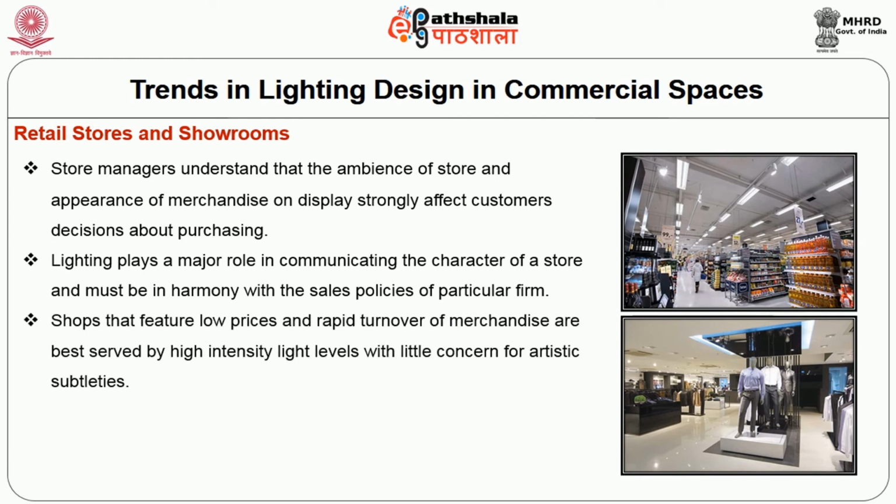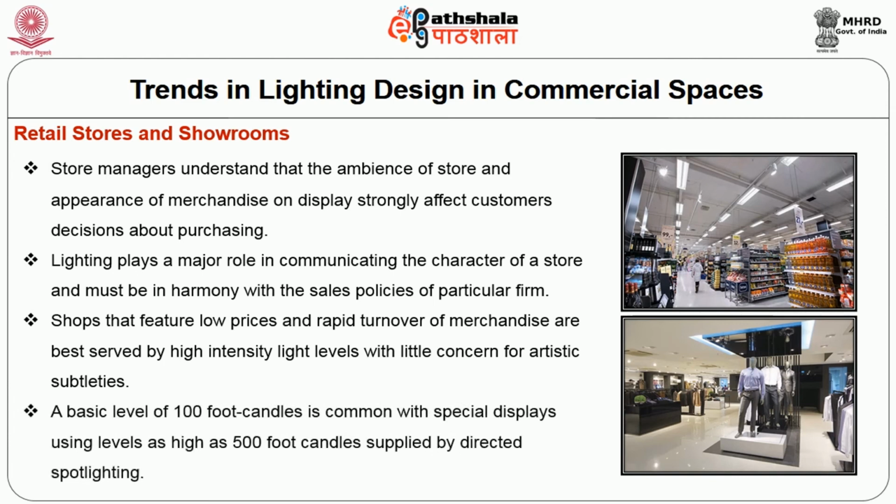Shops that feature low prices and rapid turnover of merchandise are best served by high intensity light levels with little concern for artistic subtleties. A basic level of 100 foot candles is common, with special displays using levels as high as 500 foot candles supplied by direct spot lighting.